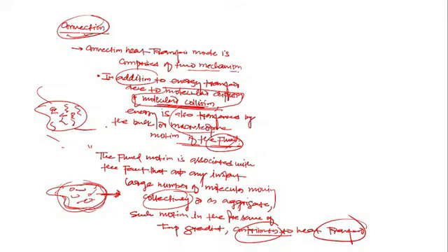While in advective flow, the transport is due to purely what? Bulk flow, that is called advection. Is this clear? Advective flow is purely by bulk motion alone. While the convective term is customarily used, it's tradition to say convection. Convection is not for heat transfer only; it's a convective term, and from it the mode of heat transfer gets its name, convective heat transfer. But under this term, two types of transport exist, convective and advective. Convective involves the combined transport of random motion and bulk motion. Advection is the transport due to purely bulk motion. There is no molecular motion involved. That is called advective.